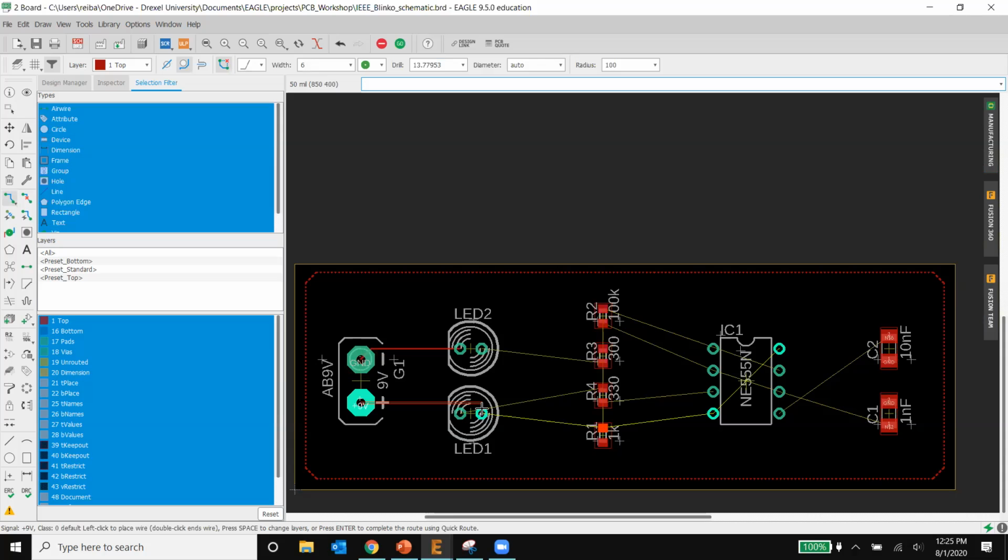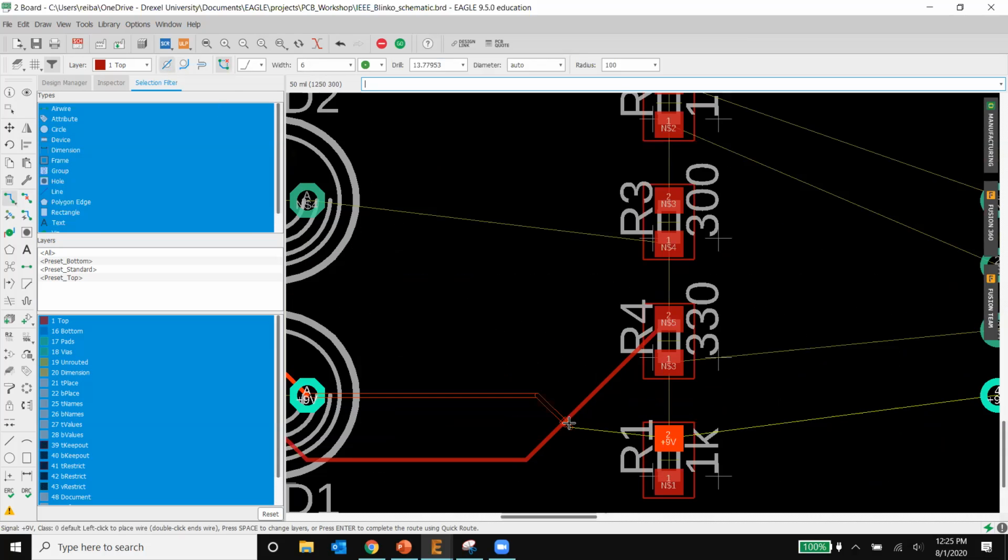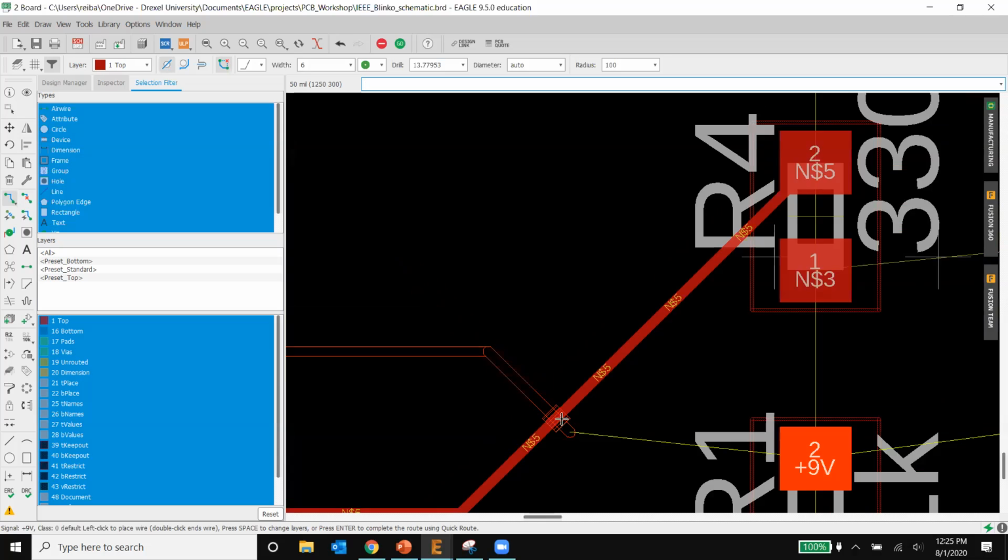Okay. Now I want to route from here. So if you see, I'm probably gonna have to cross these two lines here. So I'm just gonna make this connection here for now, and I'll figure out how to change this one. So I will start with this. And here it said, let me click this, ignore. So if you press ignore, you can see that there's a thermal connection that the DRC does not allow.